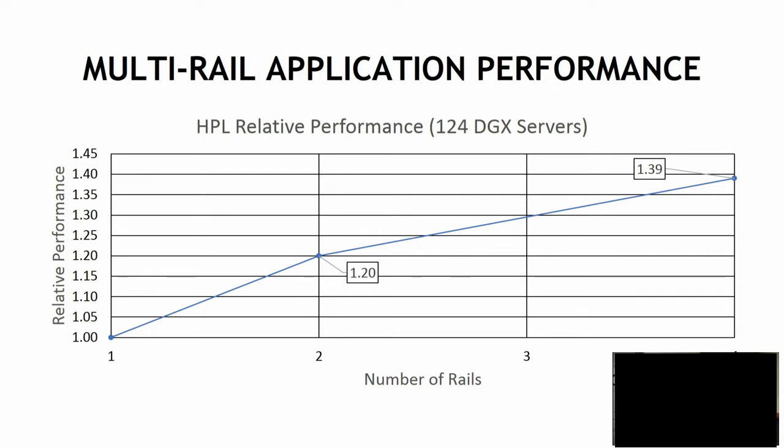Questions? Yeah. Do the rails use separate PCIe links to whatever node they're on? Or are they dual cards that share the same? So the question was, is it shared ports or are they individual cards? I think I didn't put the diagram in here today. They are individual cards. They have individual PCI Express connectors. And those connectors are off of a PCIe switch that is not going through the CPU. So when the GPUs are communicating, it passes through without going to the CPU. It just goes through one switch to another switch to the device. So we can avoid transferring through the CPUs.